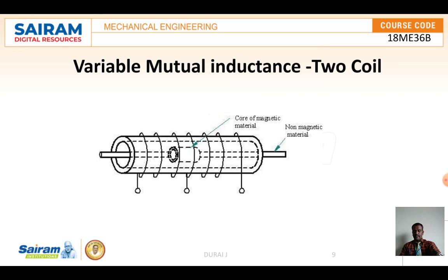Here the detector portion, an electronic micrometer, uses inductive coupling between the coils, which depends upon the magnetic flux path changing with the relative position of the permeable material. A variation of this can be used in a transducer for measuring small internal diameter. So for this, the variable mutual induction coil has to be used.